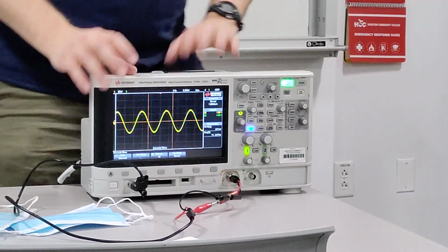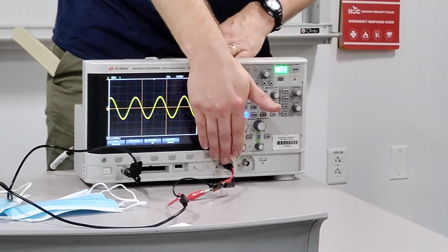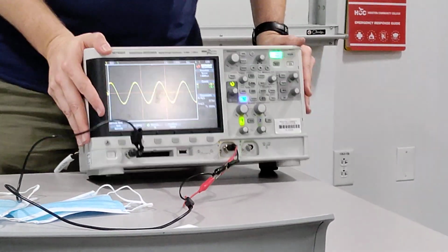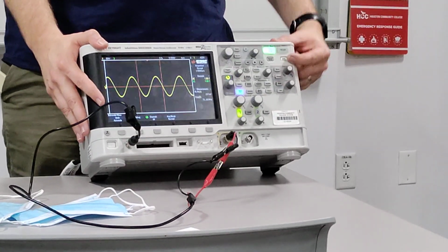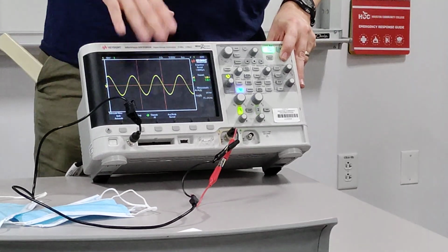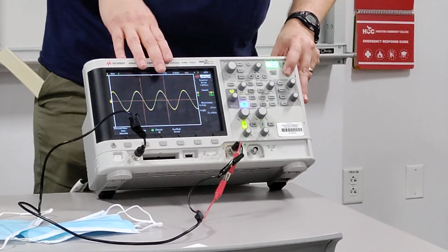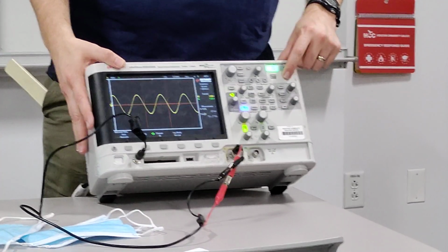There we go. Okay, so I have a sine wave outputted from the function generator into the oscilloscope, channel 1, and I've just hit a button that's very important. It's down here, it's called auto scale. 99% of the time, it'll just do what I've just done and have a stationary image that's repeating itself a million times a second, who knows. That button almost always works.